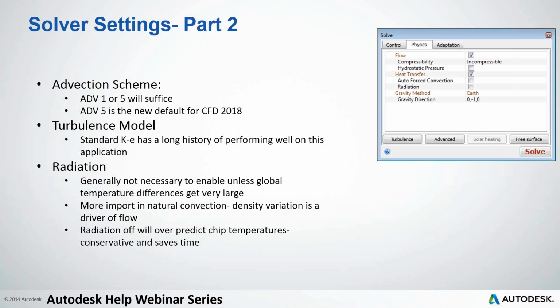It's a good question, and it really comes down to, as the engineer, do I need the physics there or not? Is it a waste of computational resources, or is it really critical to have it enabled to see those effects? I generally do not use it on forced convection problems.